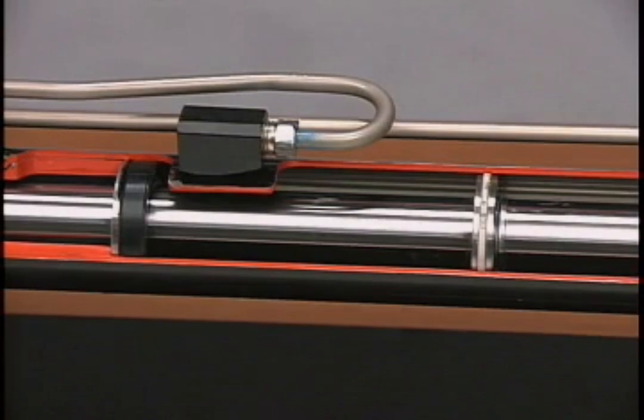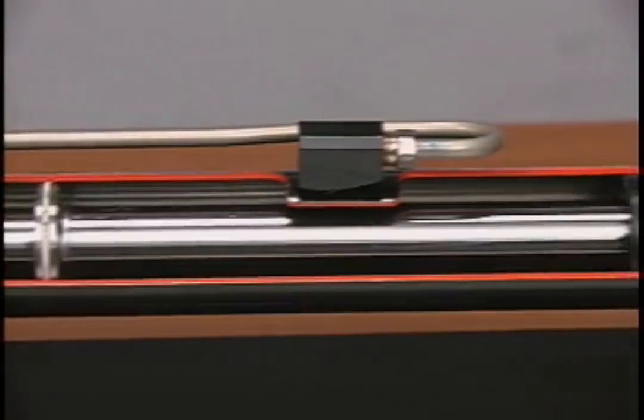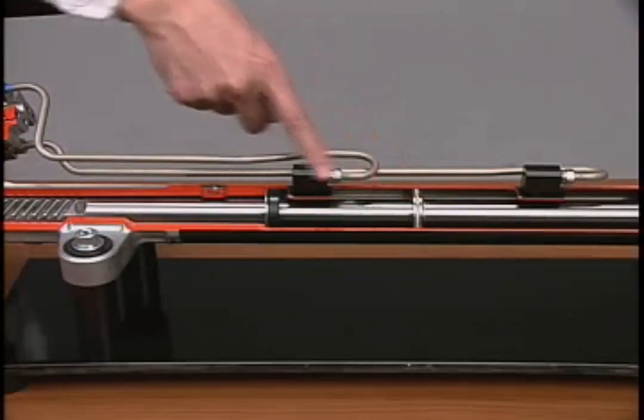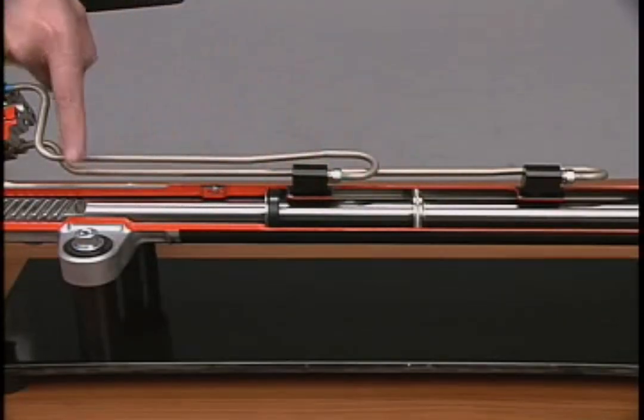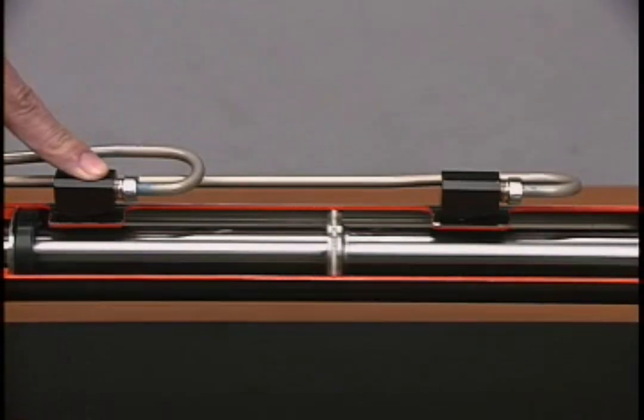The power cylinder contains a piston. There are chambers to the left and right of the piston. The piston is connected to the steering rack. It assists the action of the steering rack when supplied with the hydraulic pressure.